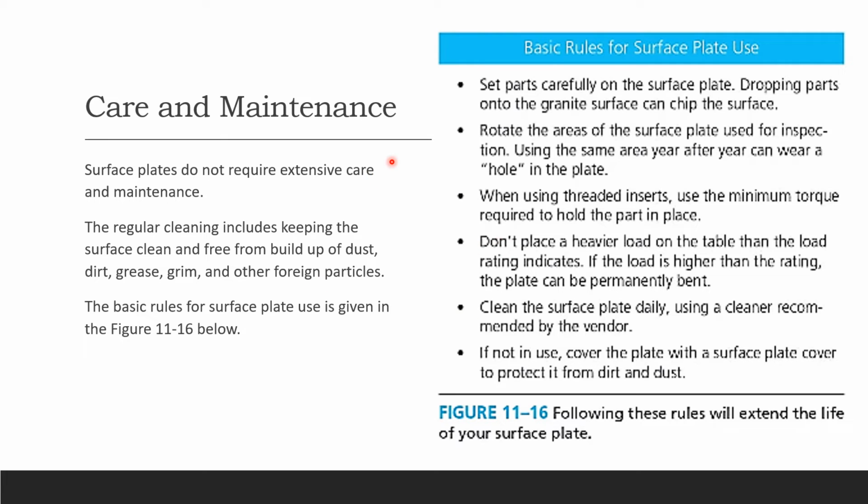Care and maintenance. So here are the basic rules for surface plate use. You can just read it, I don't want to read everything for you. I'm just trying to tell you to set the parts carefully on the surface plate. Dropping the parts onto the granite surface is going to chip or nick that surface. You also need to rotate the area of the surface plate used for inspection. Using the same area year after year can wear a hole in the plate, so you will definitely rotate the area, just like you rotate your car tires every 3 months.